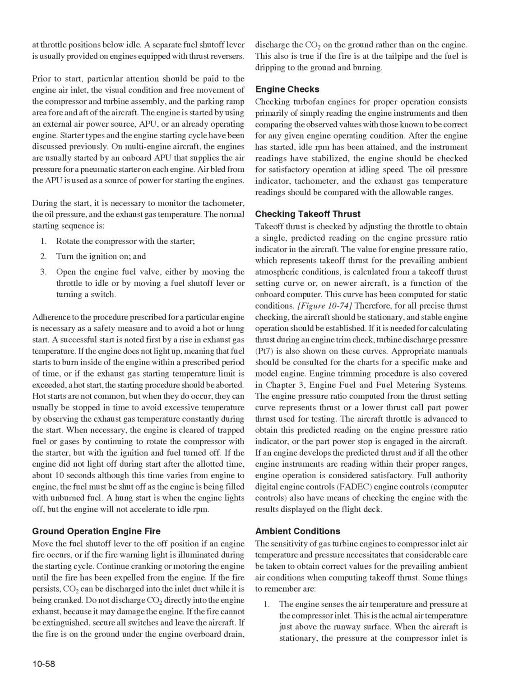A successful start is noted first by a rise in exhaust gas temperature. If the engine does not light up, meaning that fuel starts to burn inside of the engine within a prescribed period of time, or if the exhaust gas starting temperature limit is exceeded, a hot start, the starting procedure should be aborted. Hot starts are not common, but when they do occur, they can usually be stopped in time to avoid excessive temperature by observing the exhaust gas temperature constantly during the start.